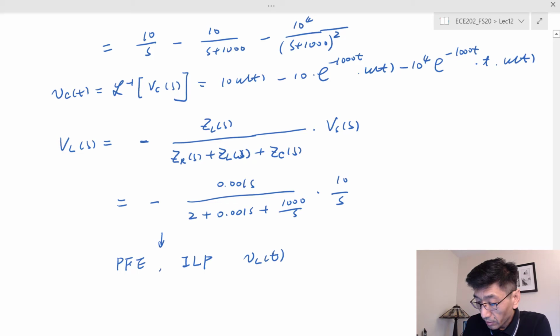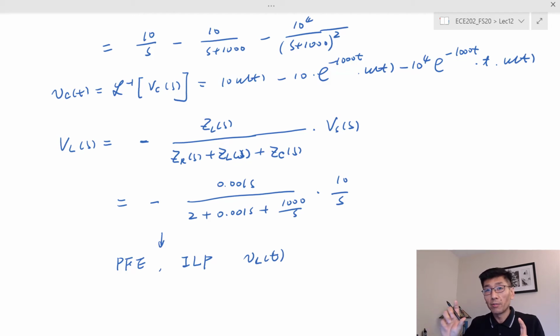Okay, so that's for the voltage division. I hope this example illustrates that when you apply the voltage division rule, you need to be very careful. You will find the voltage across a particular element with respect to the total voltage you are given. If both voltages are voltage rises or both are voltage drops, in that case you need to put a negative sign, right? Otherwise, this should be a very easy rule to apply. I'll see you in the parallel connection.